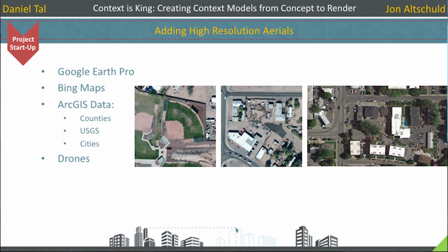And finally, the last one, drones or planes. Depending on really the budget of your project and size of your project, you can actually fly either a drone or plane and get custom LiDAR and custom orthorectified images that are then current and good for your site.